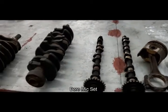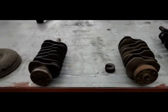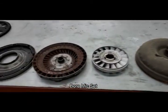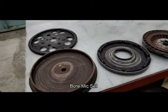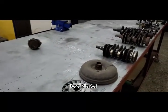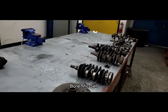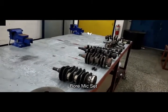Students are asked to measure and draw the component. Tools, measuring devices, vices, tables are provided to execute this task safely and efficiently. After this, we proceed to do a hardness test followed by a spark test. The spark test is done to tell what type of material it is. Students work as a team to complete the given exercise.